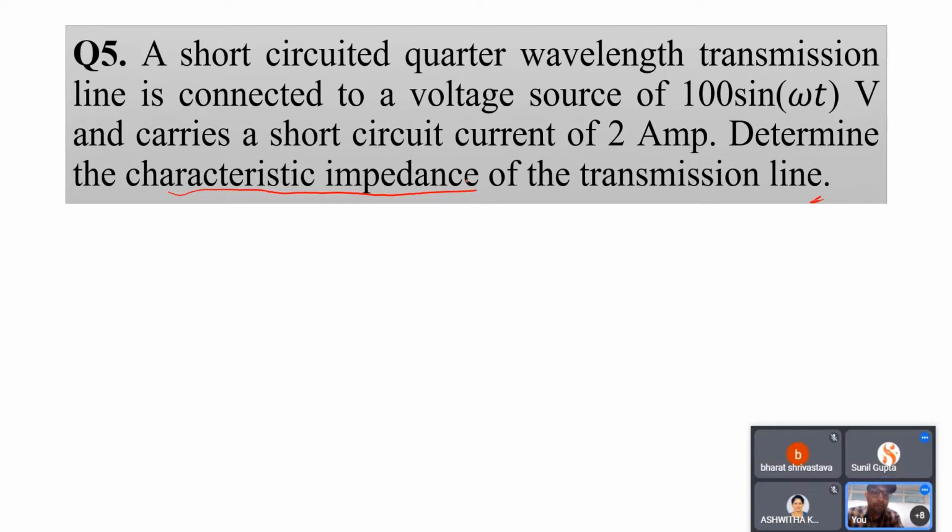No, actually these two terms are different. Whatever the input impedance will be, it will not be the same as the characteristic impedance. I know what input impedance is and what characteristic impedance is. From impedance transformation, as we had derived the input impedance from the impedance transformation formula, similarly if Z input is known, which is near about 50 ohm, from there we can calculate the characteristic impedance, where the load resistance is zero.